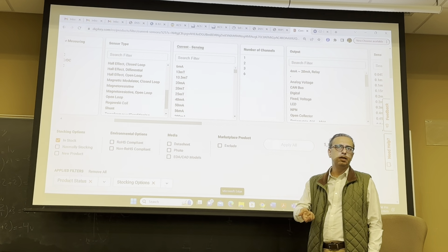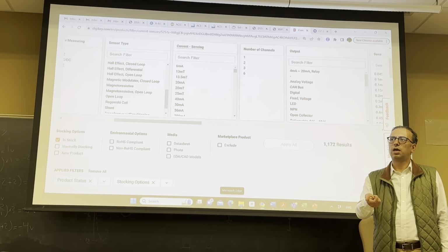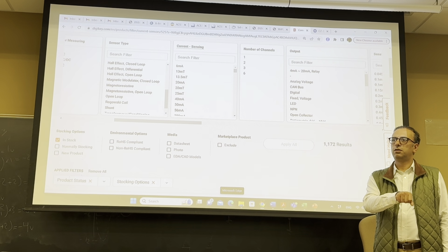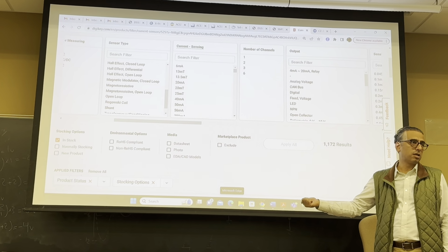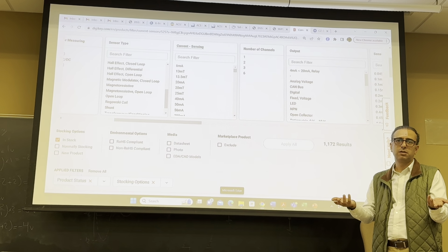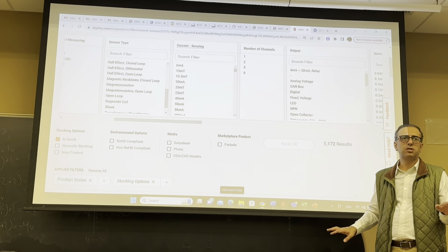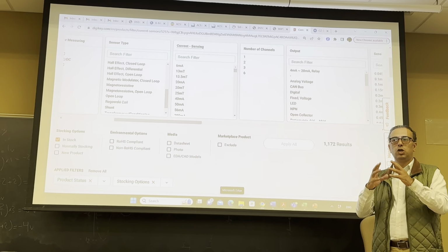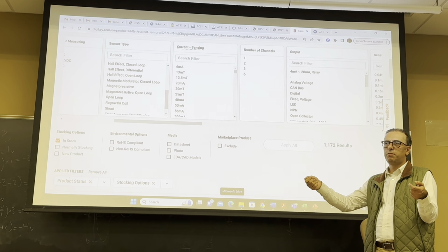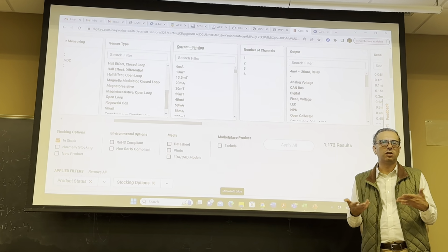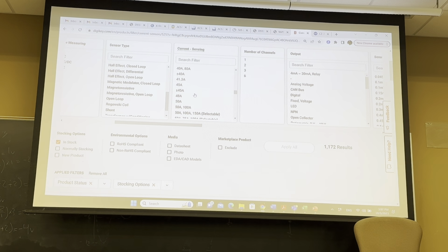So if you pick 80% duty cycle, 30, 24, 3, basically it's about 5 or 6 amps you need on the AC side, right? So 5, 6 is the range that you're good with. So I go with 10 amps, for instance, right? So 10 amps is the maximum. If you want to design to use it later with one of our PV panels, maybe you want to go all the way to 300 watts, right? Measure the current and go to the maximum, which is like 20, 25 amps. So in other words, you don't need a 6 milliamp version, you don't need thousands of amps, right?